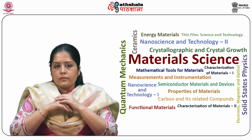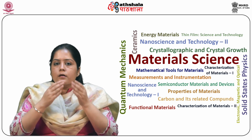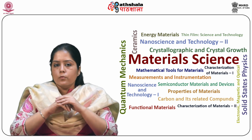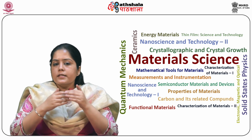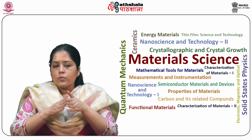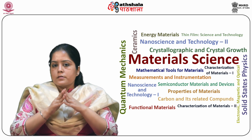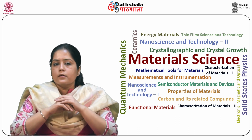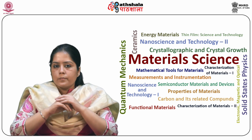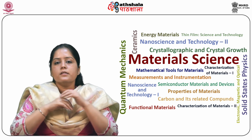Surface preparation. The surfaces of the crystals grown by many techniques are not smooth and there is some damage at the surface. Smooth, clean and damage-free wafer surfaces of silicon can be obtained by chemical etching, which improves the cell efficiency and durability.